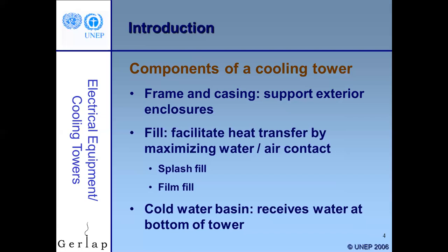It's possible to retrofit a tower if the fill gets torn up over time by ice and chemicals and things like that, and just structurally it can break. It can be taken out and replaced. It's a fairly big job, but it can be done, and you can upgrade a tower from, say, a splash fill to a film fill, at least some of them. You have to check with the manufacturer to see if that's possible. If you do that, you're probably going to get better performance out of the tower than it was initially designed for.